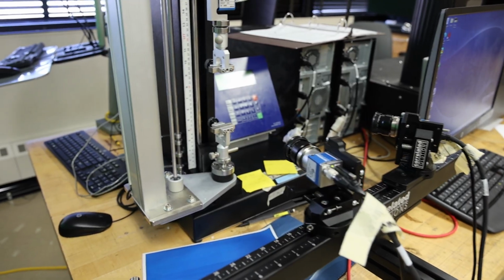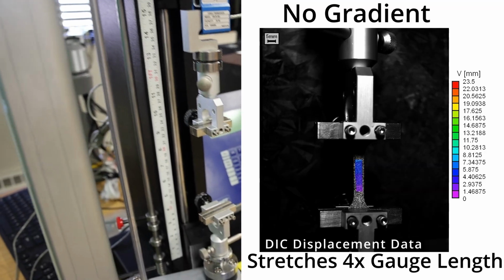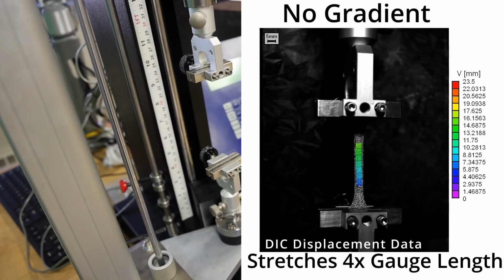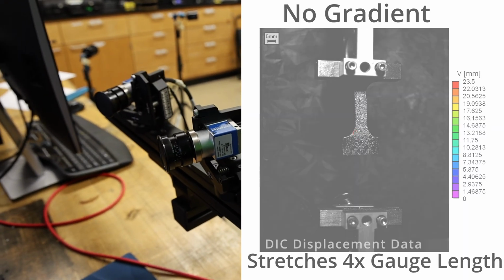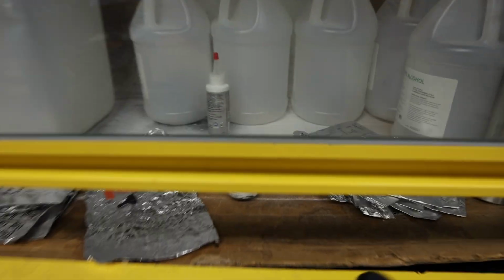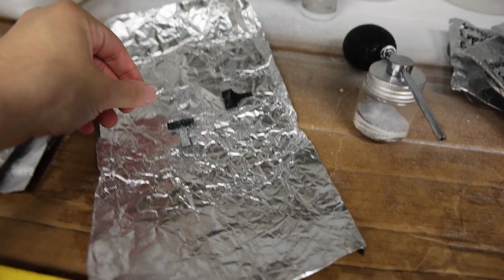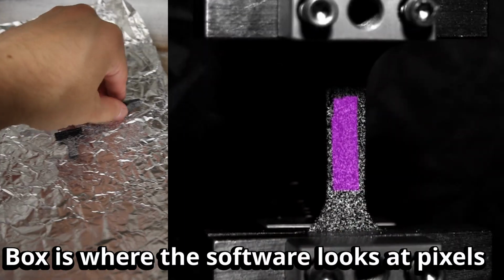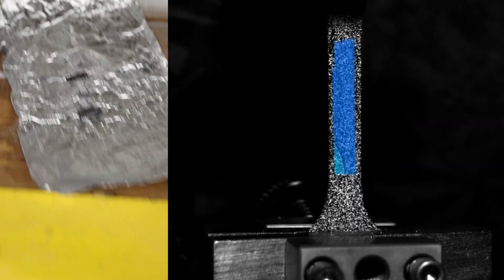Now, our parts have a problem. They are extremely elastic, so when they are being pulled apart at the tensile bars, sometimes we can't really tell what the stress and strain is on the parts, which is the reason why we use these, which are two digital image correlation cameras. Now, what is digital image correlation? Well, what you do is you take a part, and for instance, you speckle your part with white and black. And when your part is going to be stretched, like this one is, these cameras will detect how far apart these speckles have gone away from each other.